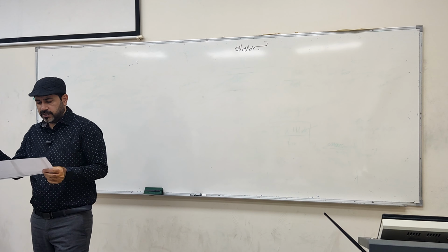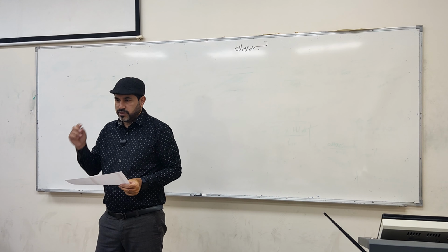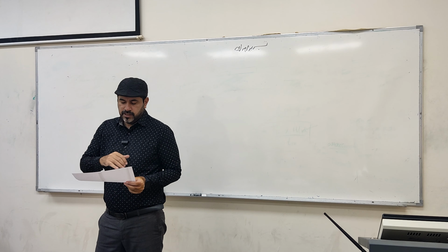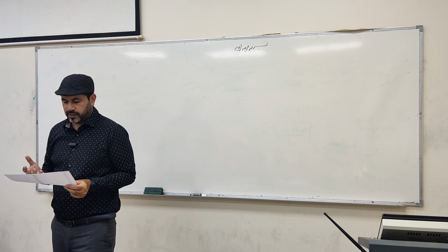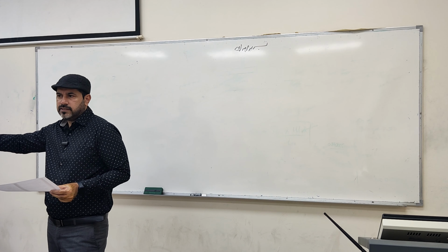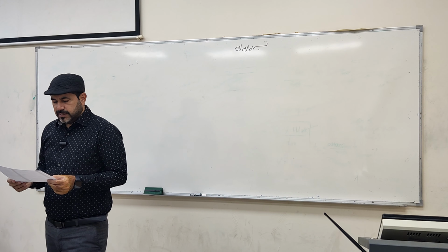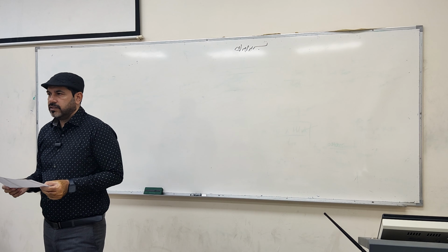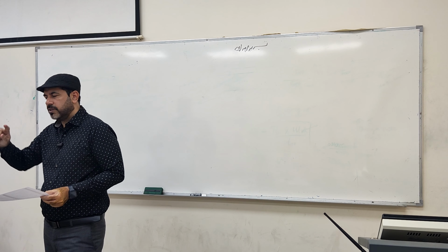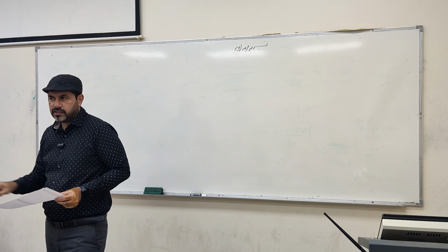Sometimes you have this accompanied graph, and sometimes you do not. So you need to read the information, extract the input data and draw it by yourself. So it's a turning moment diagram. On the x-axis we have angles, and on the y-axis we have turning moment. Thus the cycle is complete in 4 revolutions, which means 8 pi, because each revolution is 2 pi: 1, 2, 3, and 4 revolutions.